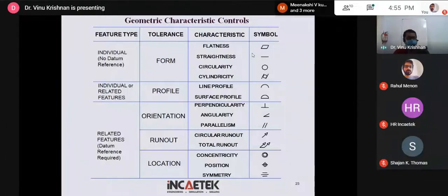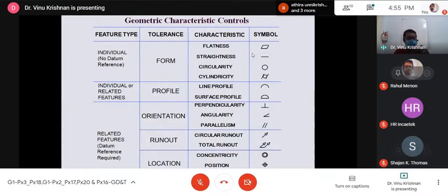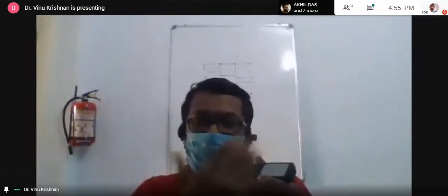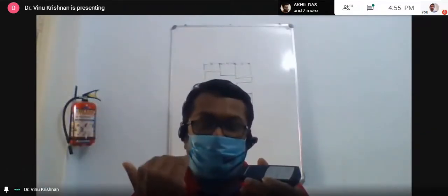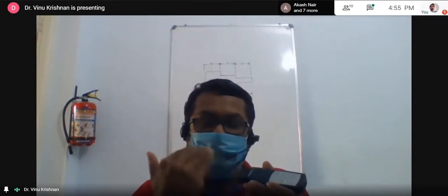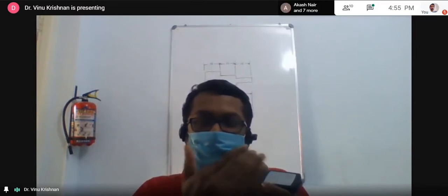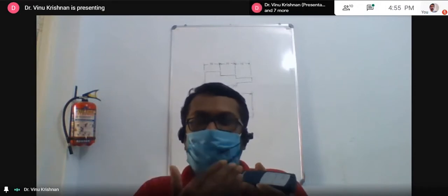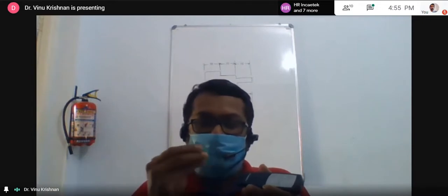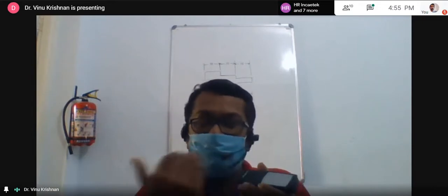First, finish. Flatness means much more than that. That means it's over a length, so it has a much longer length, or it's called the waviness. So how the surface is, is based on manufacturing basically. So if there is a tool chatter or vibration, this waviness will increase.